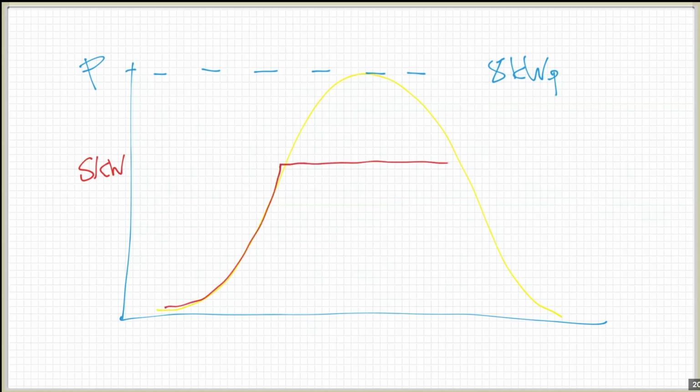So the inverter would do this. It would go up. So it's actually not going to produce that bit up the top there. It's going to clip it because it's controlling the current flowing into its maximum power point tracker. So it just chooses not to use the full power of the array. So you're not blowing it up. It's not dissipated as heat somewhere else.